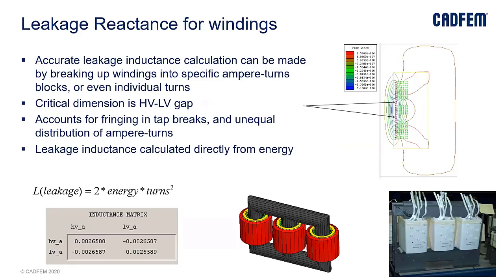And here is one more added advantage of this Ansys solution: it can compute the short circuit impedance, which we'll treat as the leakage inductance. To model this kind of application, we use a turn-by-turn model, where you can see we are using a rotating-about-the-Z coordinate system sketcher, modeling each and every turn. We can model the specific ampere-turns, which will help us understand the accurate behavior of these flux lines, or this leakage flux.